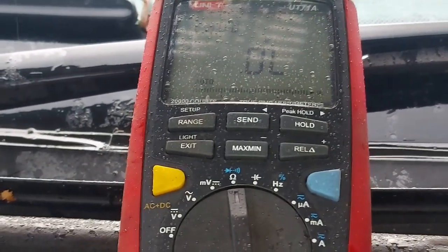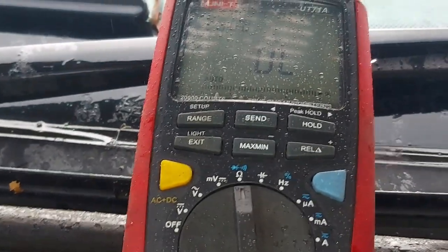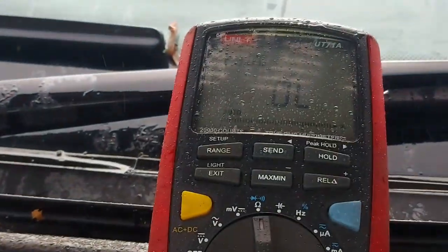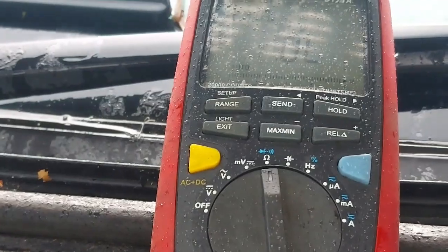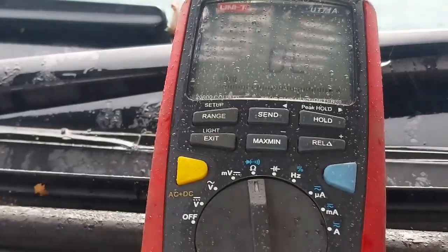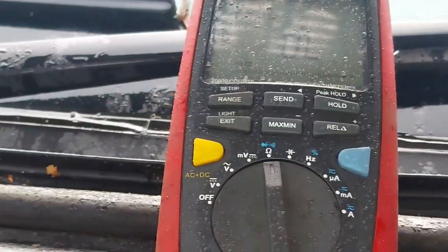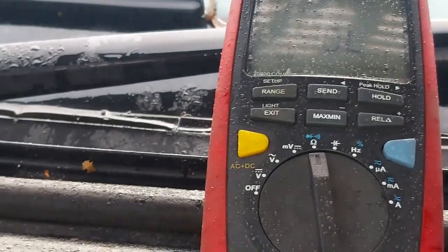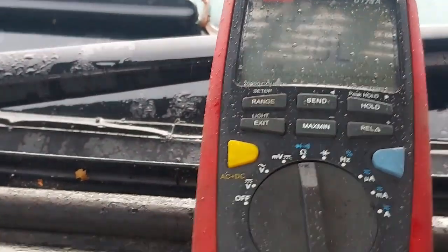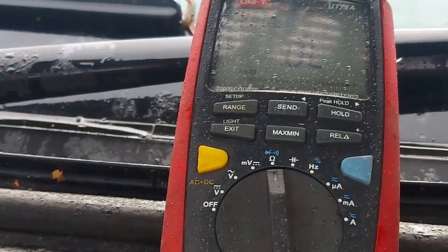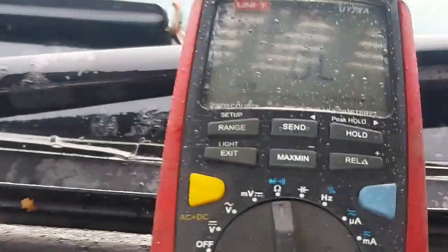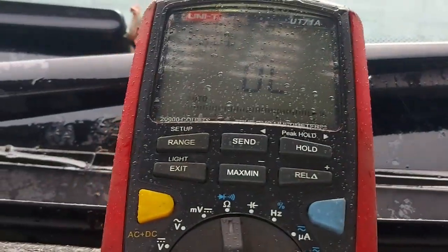I will definitely put a sensor. There's something going on with my sensor here. So that little resistance, the difference between the two, one is 500 and something, the other one is 200 and something. So that difference might be causing me this problem that I have. So I'll get a sensor because my wires are not open, my wires are not shorted. So I will get a sensor, and it remains to be high resistance. Remember what I always tell you, if it's not an open, if it's not a short, it is high resistance. So I think that's where we are.